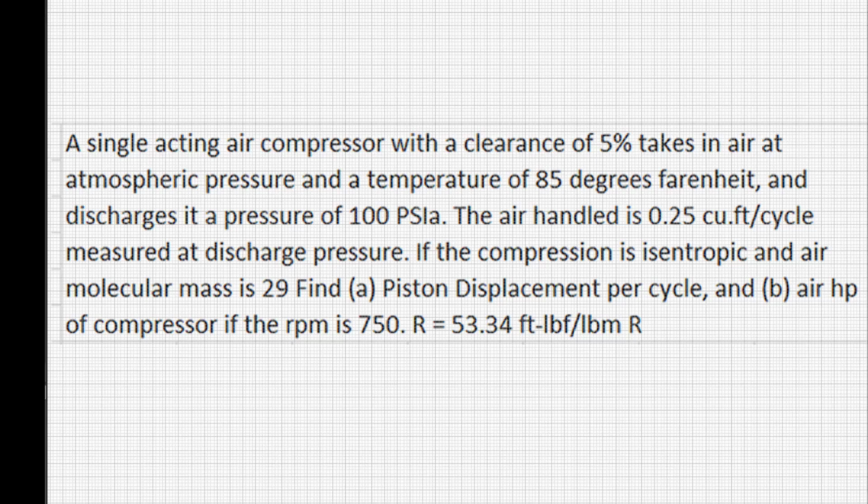And for the problem, we have here a single acting compressor with a given clearance of 5% that takes in air at atmospheric pressure and a temperature of 85 degrees Fahrenheit. And it discharges its pressure at 100 psi. The air handled is, we have the given of 0.25 cubic feet per cycle measured at the discharge pressure.